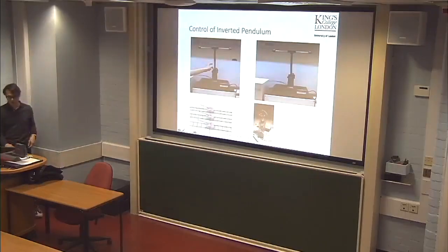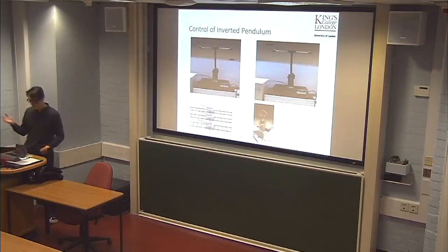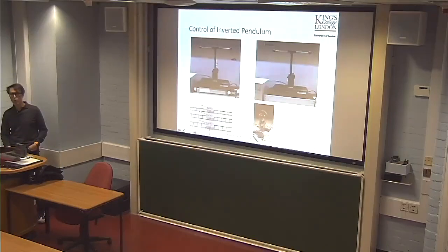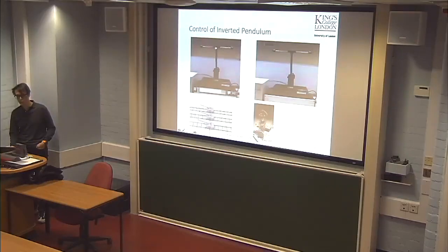Anyway, take a look at the applications. The first one is a benchmark model, the inverted pendulum. We use 16 models to represent this system, and this application is about stabilization. That means we are going to return the pole to the angle 0. The force is applied to the joint, about this rod. We have a motor right here. The motor drives the rod left and right in order to generate the force, so that we are able to balance the pole. We call this the regulation problem.